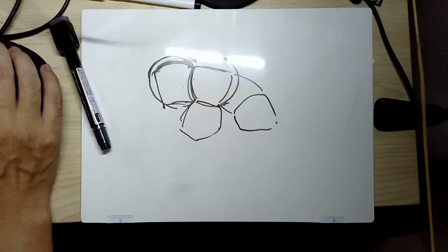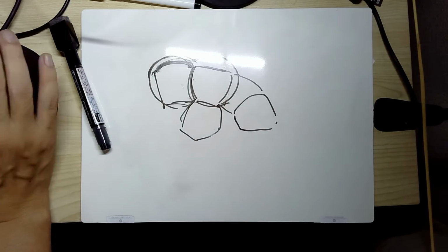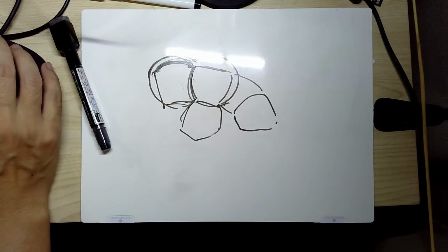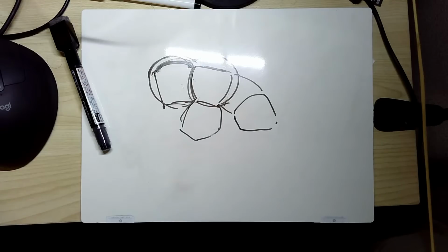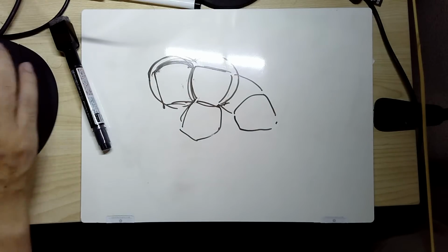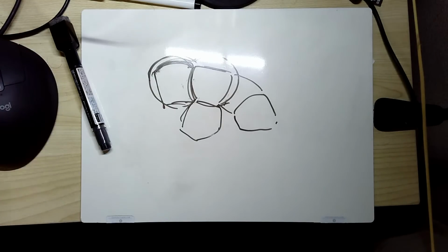So the wall for this cell here and the wall for this cell at this position should share the same point numbers as well as point positions. Okay, so the best way to achieve that is using subdivide, I think. I'm going to use subdivide for each cell to create the inner wall division.